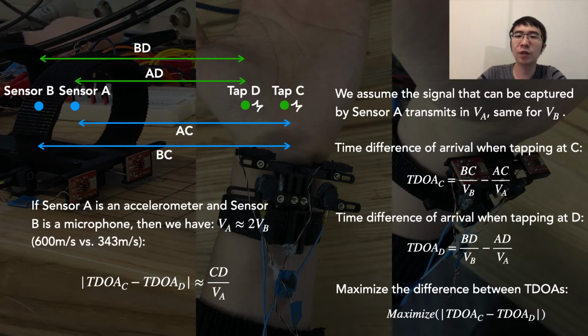However, if sensor A and sensor B are not the same, let's say sensor A is an accelerometer and sensor B is a microphone, then propagation through a wooden surface is about 2 times faster than propagation through the air. Plugging this relation into the formula, we get that the difference between the two TDOAs is not 0 anymore, it's CD over VA. We actually add extra time difference by using two types of acoustic sensors.